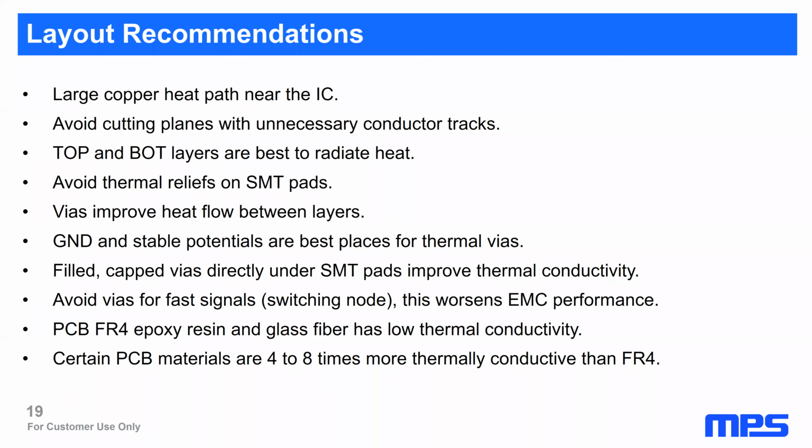Top and bottom layers are best to radiate heat. Avoid thermal reliefs on SMT pads, especially for the ceramic capacitors. They are large, and most pick and place machines and soldering machines nowadays don't need the thermal reliefs anymore.